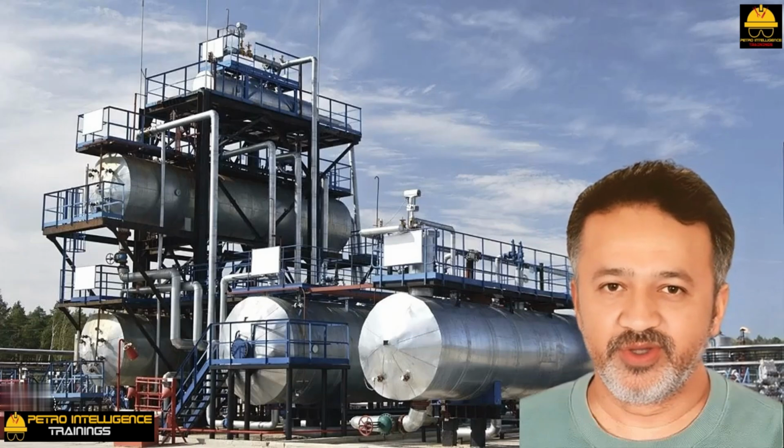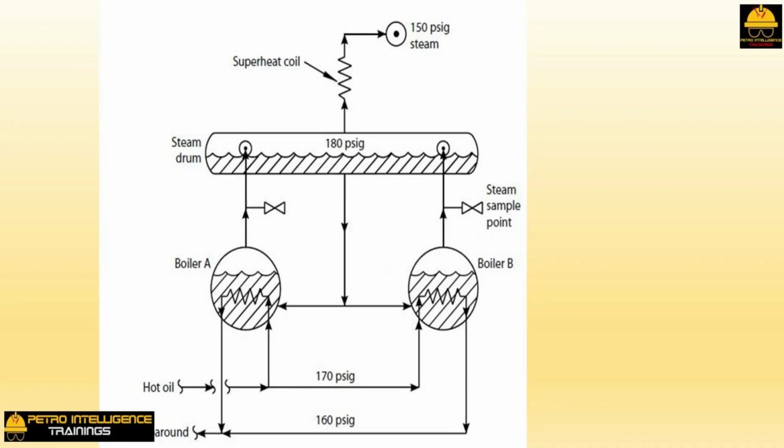Identifying waste heat boiler tube leaks. This picture shows 2 waste heat boilers that are generating superheated, 150 psi steam from a fractionator hot oil pump around. After years of trouble-free operations, water was observed in the gas oil pump around return stream. The symptoms of the water infiltration into the fractionator were an increase in the fractionator pressure and an increase in the water production from the fractionator reflux drum's draw-off boot.